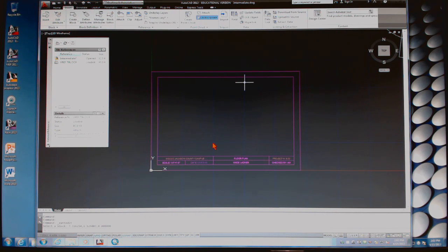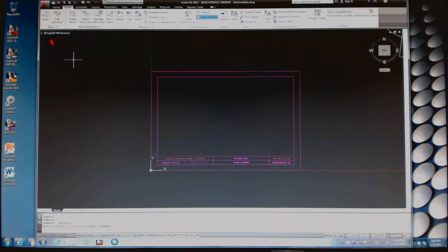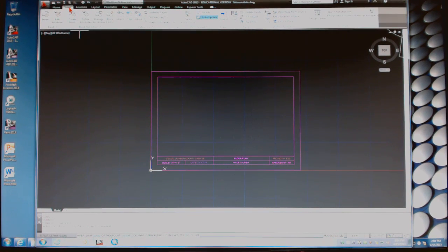DC spacebar is the keyboard way. Well, let me ask you real quick. How do I get this one up? This tab right, this X reference box. XR. Remember that. Just to do an X reference, this is the easiest way to do it with your title. You need to do DC spacebar for Design Center. We're going to insert tab all the way to content, and you see Design Center is right there.